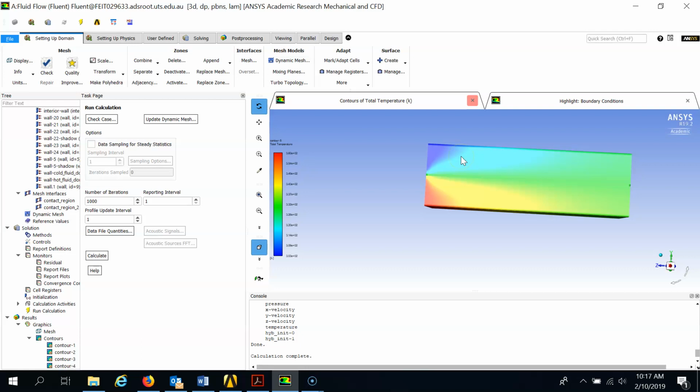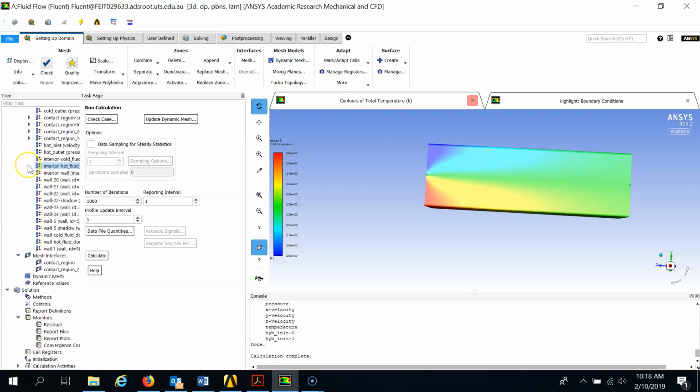So the thing is, when we used the turbulence model we found no heat transfer from the hot fluid to the cold fluid, but now when we change the model from the turbulence model to the laminar model, we found that heat transfer is happening. So you need to play with these options, and I also changed the flow rate. I made it 0.05.